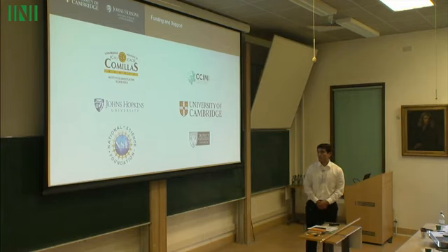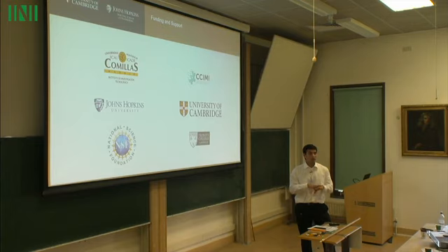Yeah, absolutely. So Jensen's model is the state-of-the-art strategy that is used for modeling the wake. But up until this point, either the model hasn't had rigorous statistical bounds placed on top of it, or people haven't tried to understand the underlying curves that make up the Jensen's model. So we were the first group that went out there and said we expect the underlying model to be this exponential decay model.